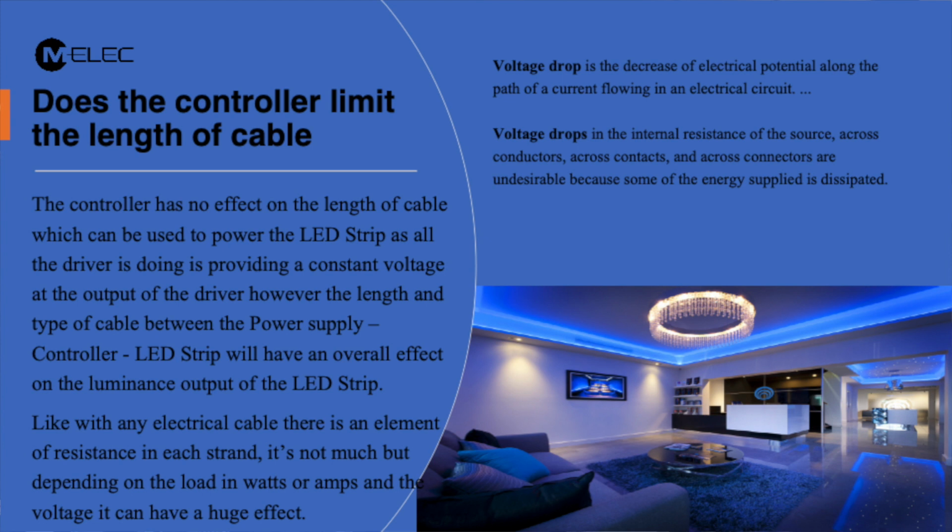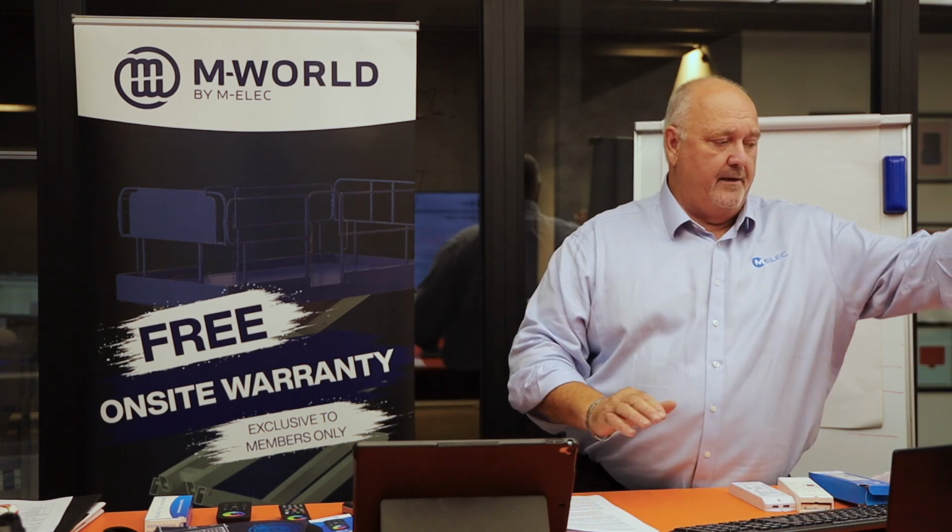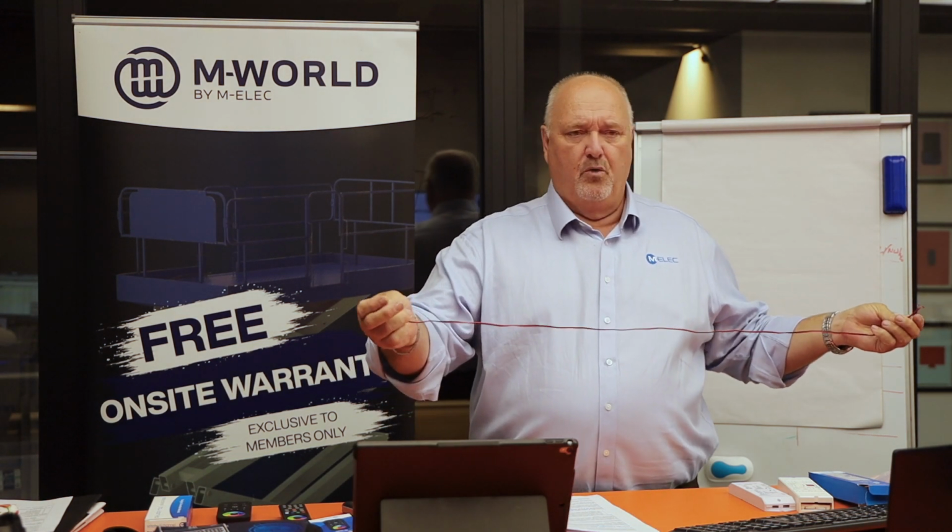Does the controller limit the length of the cable? Again, no, it doesn't. The controller doesn't have any control over the voltage drop that you will get. And here's something for you. This is the normal cable that would come with your LED strip, and it's very, very tiny, a 0.32.